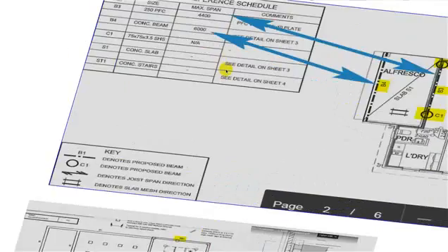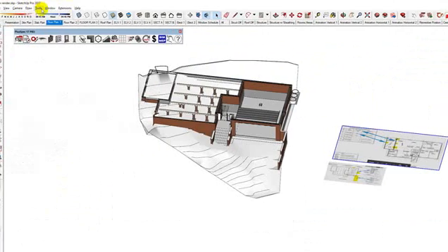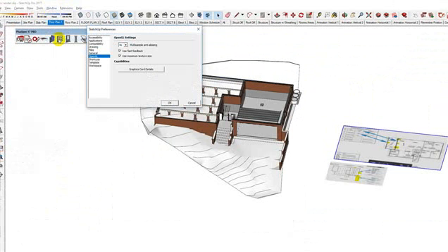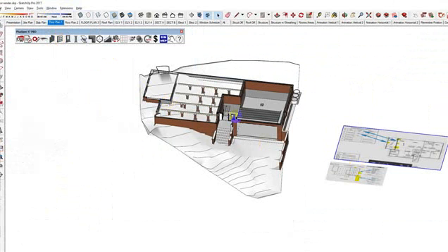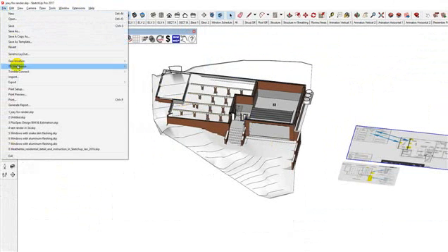And I'm just going to put them here. Now, one thing, the resolution is good, and you explained before that you couldn't read the text. The reason being is you need to go to Windows, Preferences, OpenGL, use maximum texture size. Then that way you'll be able to get it in quickly. So file, import,